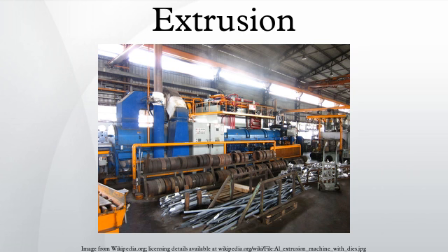Drives. Most modern direct or indirect extrusion presses are hydraulically driven, but there are some small mechanical presses still used. Of the hydraulic presses there are two types, direct drive oil presses and accumulator water drives. Direct drive oil presses are the most common because they are reliable and robust. They can deliver over 35 MPa. They supply a constant pressure throughout the whole billet. The disadvantage is that they are slow, between 50 and 200 mm per second.